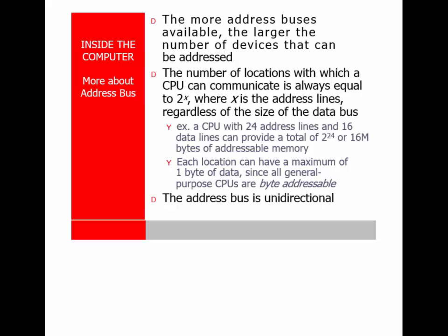The larger the address bus, the larger the devices that can be addressed. Now, memory chips come in multiple sizes. We'll talk about that. You can have an 8 gig module. I haven't seen 32 gig modules, but I've seen some 16 gigabyte modules. That's usually 9 chips on one module. And depending on the motherboard, you might put them in pairs or you may put them in singles.